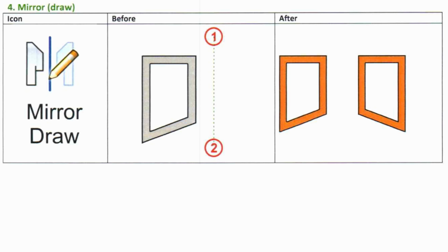Keynotes: use when no existing reference, grid, level, or edge is available. The mirror axis is defined by a vector between 2 mouse clicks. Works well for irregular layouts or diagonal symmetry. Best practices: be precise with your 2 clicks. They control both direction and orientation. Use Tab if needed to cycle through potential references. Avoid holding Tab or moving the cursor during the operation.